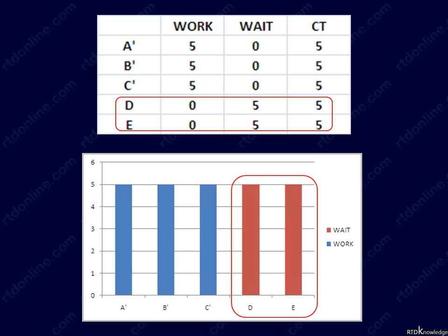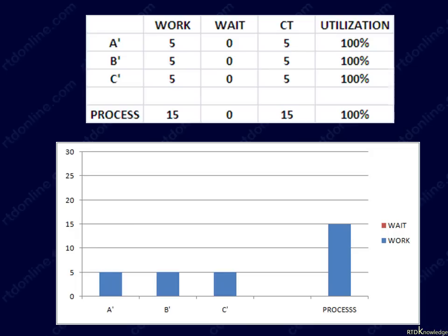If we just reduce everybody's cycle time without totally eliminating his working time or idle time, it's not possible to right-size or downsize because all five would be needed to complete the process lead time. In right-sizing, the key is to make an operator completely idle or completely busy. This is what happens after right-sizing the lean way. Our process running with only 3 operators. It becomes obvious and easy to remove the 2 completely idle operators D and E and assign them to some other processes.